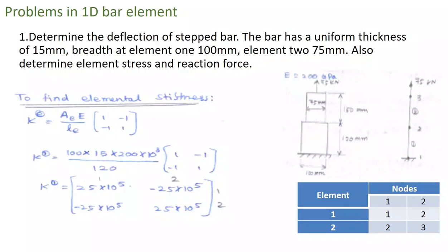So first we want to do the discretization. Based on the material properties, the discretization will be considered as a single element because they have uniform material properties. The Young's modulus will be uniform, so we won't do discretization based on that. Next, loading conditions and constraints. The loads and constraints will be acting at the ends of the object. So based on that, we need not bother to do the discretization.